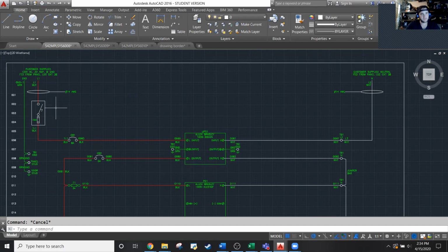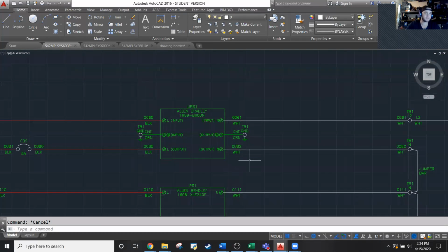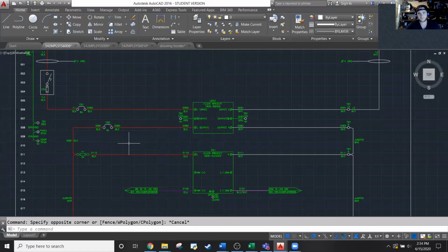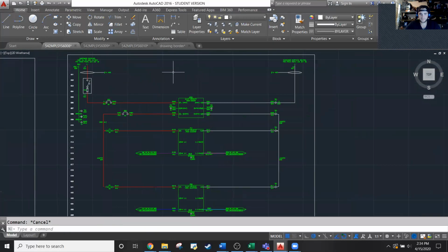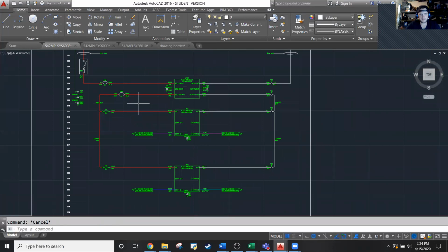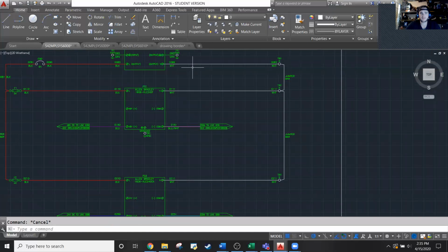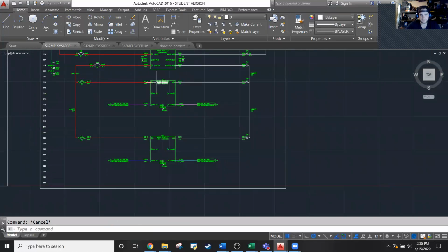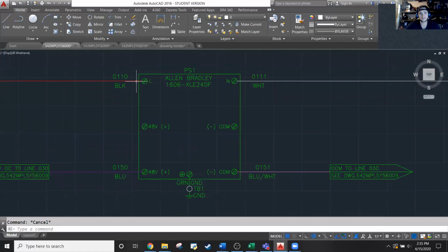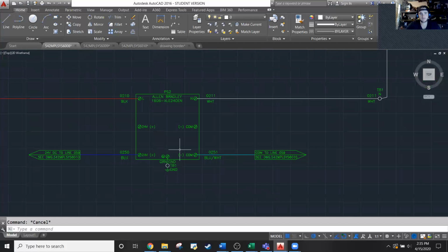This particular panel had a huge UPS, uninterruptible power supply. That was just hooked straight onto the main power input. And then from there, it went to another circuit breaker and then started distributing power. And I think in the case of this panel, everything was 24 volts. The only things we had running off 120 AC were two power supplies. Sorry, I take that back, a 48 volt and a 24 volt.